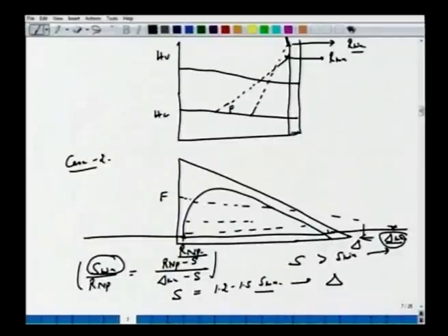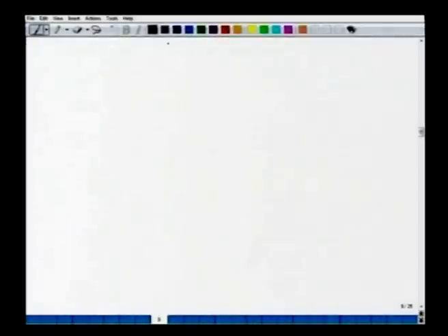And then if you increase the amount of solvent beyond this del, of course, the operating line will never be parallel to or coincide with any of the tie lines. Okay, so that's the discussion we had. We just want to summarize here one more time.